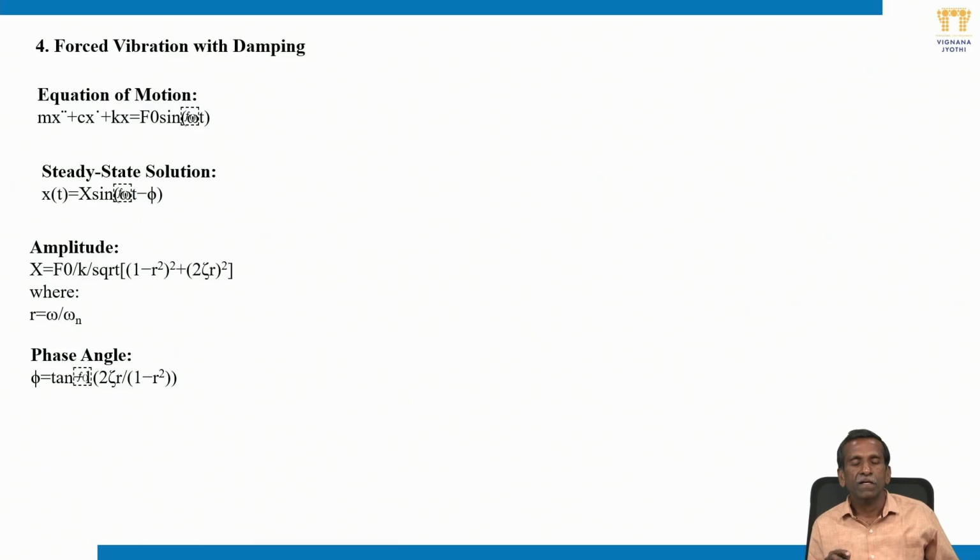From the fundamentals of mathematics, these are all second order differential equations, and if the right side equals some force component, then we also have a particular integral along with the complementary solution. We add the particular integral term if it is forced vibration with damping; without damping the terms will come accordingly.